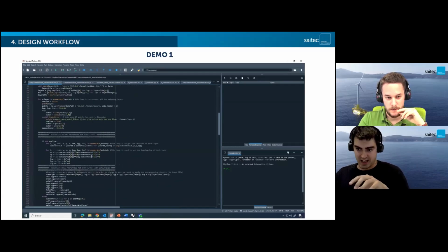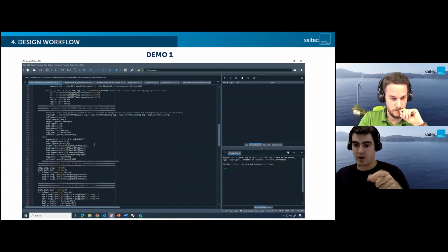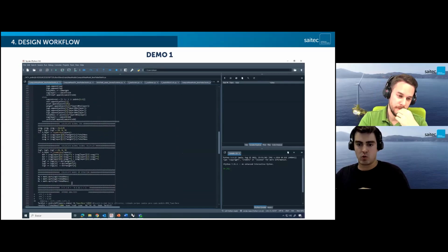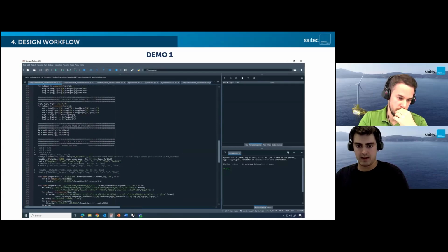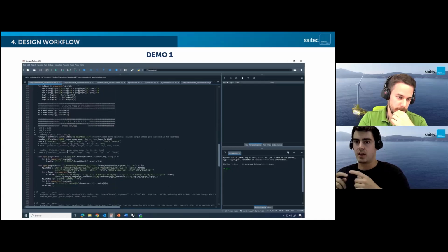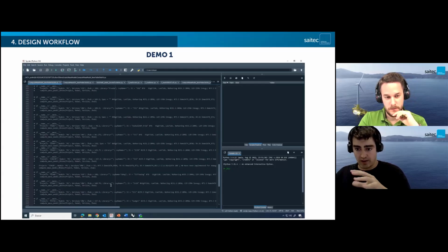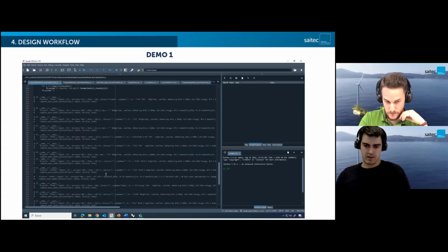So for each layer that has more than one closed polysurface, for example, imagine the plate has different polysurfaces in the layer, we calculate the physical properties of the whole element, and then we apply the densities to obtain the total mass for each layer. And we calculate the global center of gravity and the inertias. And lastly, the radius of gyration, which is what the hydrodynamics department needs for their calculations. Then we put together different results in the format that is convenient for us, and we save it.